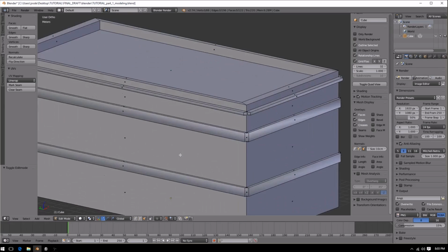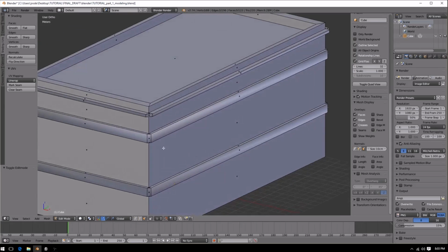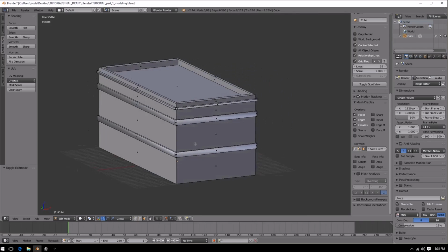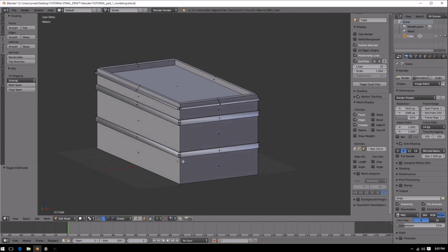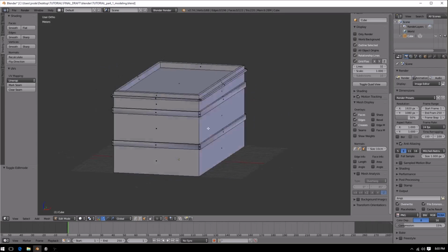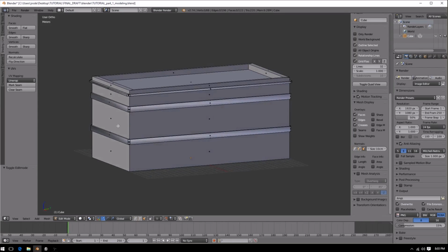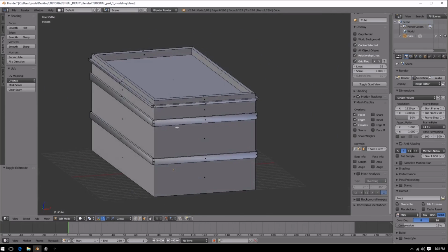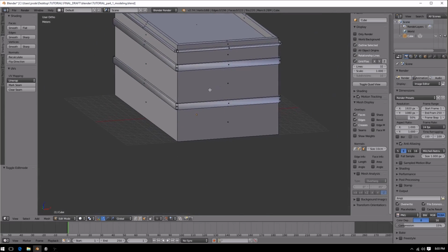Anyways, the next thing we want to do is add some doors and some extra features to this building. One easy way to do that is floating geometry. Floating geometry is adding pieces that are very close but not connected to the original mesh. What we'll do here is add planes on the front and sides that will be floating millimeters above the front faces of this wall. That'll allow us to texture this back wall of brick and texture the plane with a window shape.